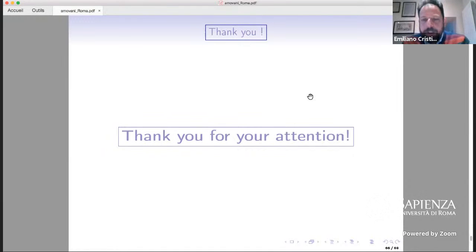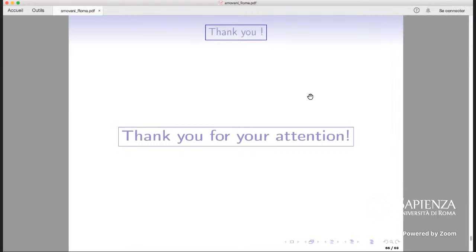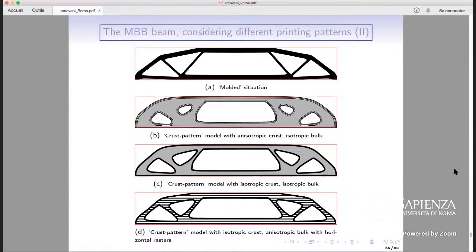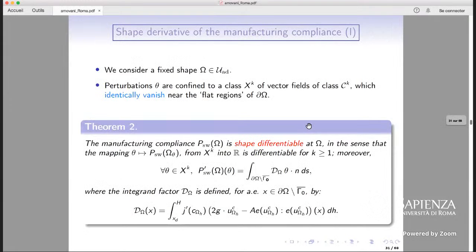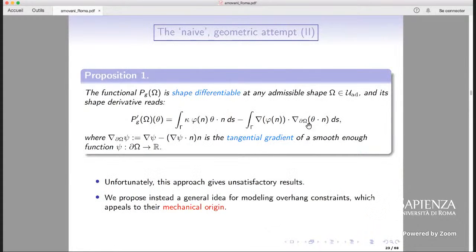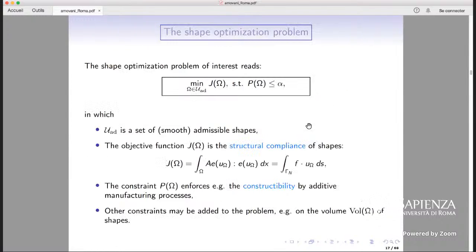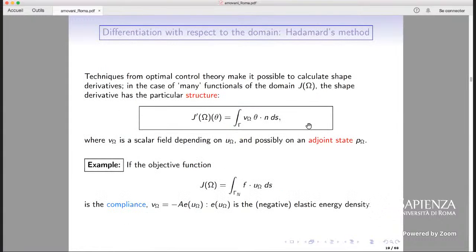So, okay, maybe Maurizio has a question. Hello, good morning. Thank you for the presentation. I have a curiosity regarding the way you apply the level set method. You derive a vector field which is moving all the points at the boundary, but this is a numerical reconstruction. So at the very end, you could end with a vector field which has a lot of discontinuities, which is not strictly allowed in the level set method. So how practically do you manage this difficulty? Because all the vector fields that are coming out in your process are derived numerically. They are not formally defined by an algebraic definition.